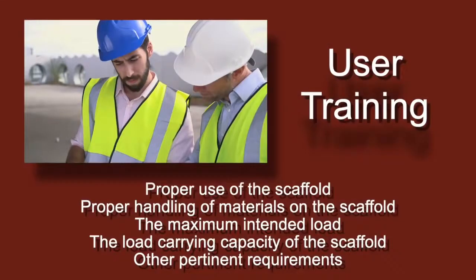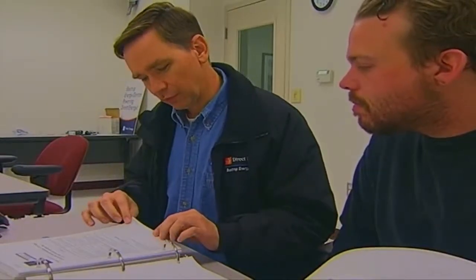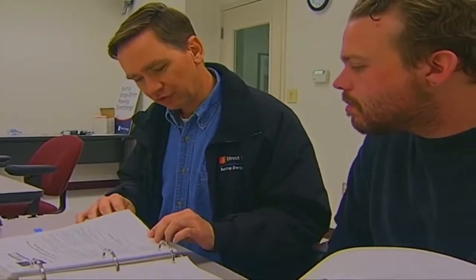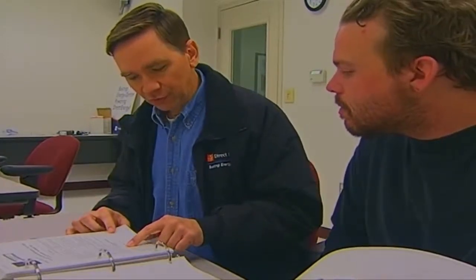Users must also be trained in the proper use of the scaffold, proper handling of materials on the scaffold, the maximum intended load, and the load carrying capacity of the scaffold and any other pertinent requirements. Employers must retrain workers when there is reason to believe that the worker lacks the necessary skills or understanding to safely erect, use, or dismantle a scaffold.